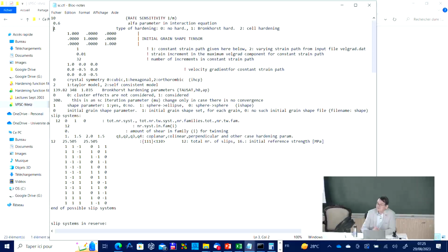But that code knows other things. So this code here is using either no hardening if you put here 0, and there is no intrinsic hardening in the material. There can be texture hardening because grains rotate into harder positions. But without hardening, we know that's so important in the material and especially in the viscoplastic self-consistent modeling that we had better do it. And this is the whole purpose today to do this exercise, to do a very good hardening simulation.